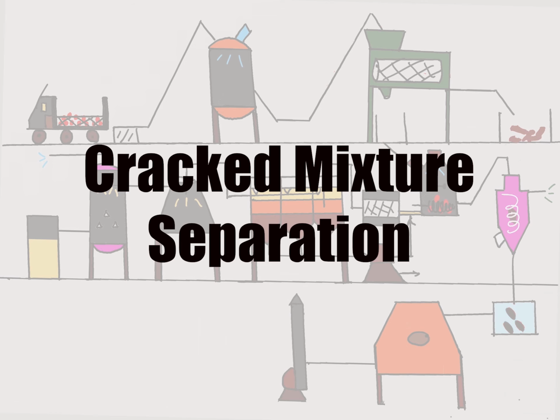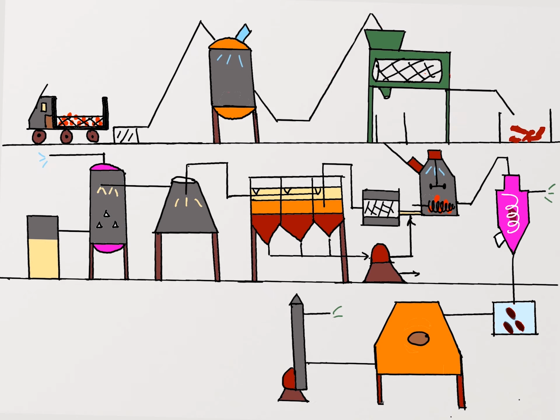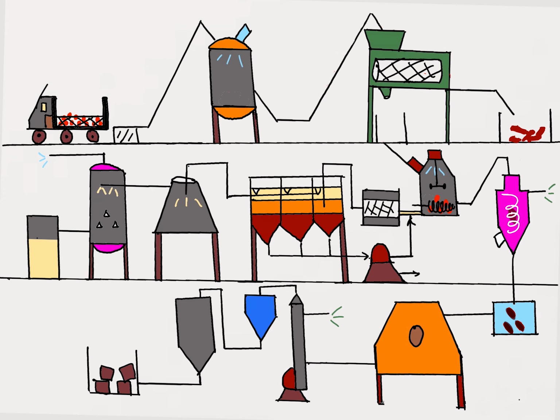The cracked mixture is separated into two operations. First, a dry operation that uses a winnowing system to remove small pieces of shell and dirt, then followed by a wet separation using a hydrocyclone to separate the kernel from the shell using centrifugal force. The last step is to dry the kernels to about 7% of moisture content to reduce the chances of mold. The dried kernel is bagged and stored.